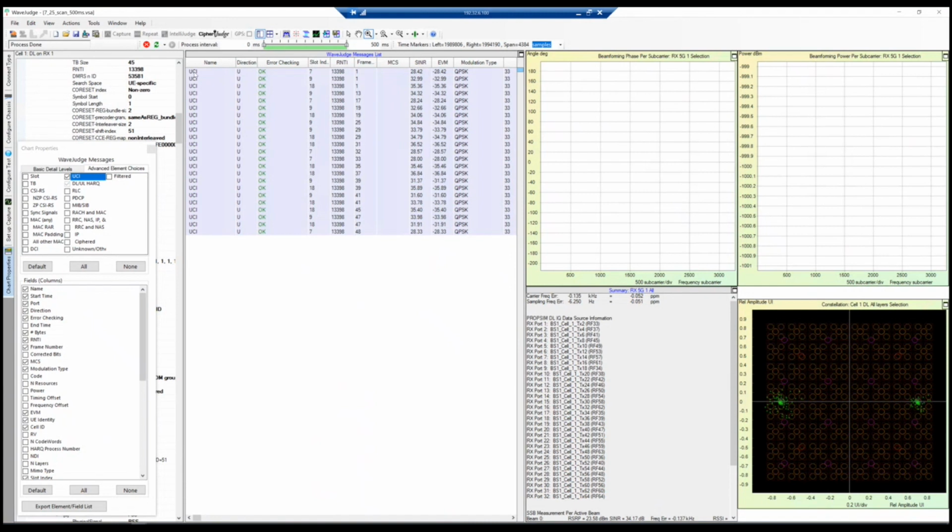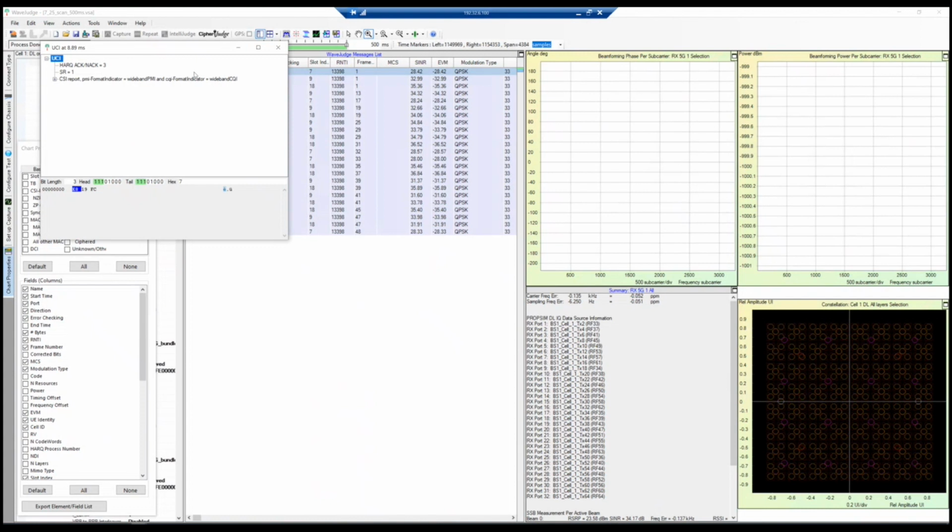and you can see here what the CSI reports. Actually, it's a rank 1, so layer 1, for example, and you can see what the PMI reported is. I11 is equal to 3, I12 is equal to 1, and I2 is equal to 3. So this is the PMI.